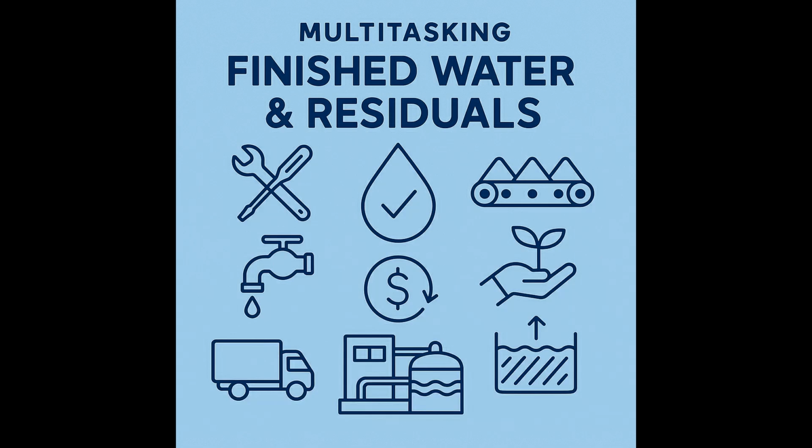The best model depends on the plant's specific flow rates, how much sludge they produce, their storage options, and their staffing setup. Automation seems like it would be a huge lever here for improving efficiency and getting that ROI. It really is. Automation can pay back quickly by reducing labor needs and improving consistency. Think about instrumentation. Online solids analyzers that can automatically adjust the polymer dose in real time, preventing waste. Or cameras. Yeah, cameras providing visuals inside tanks or on conveyor belts, monitoring sludge blanket levels or cake dryness. This takes the guesswork out for operators.